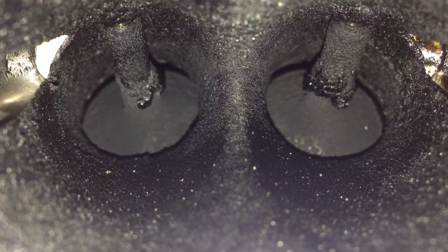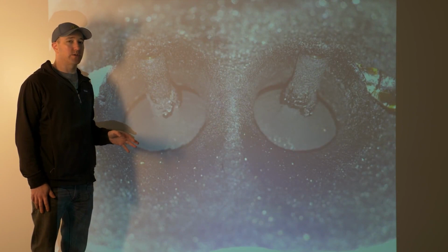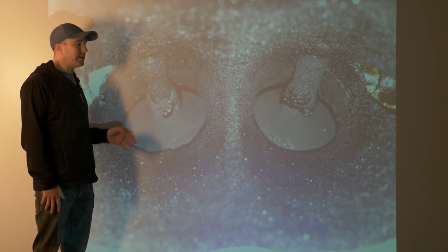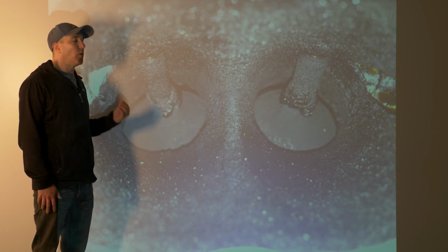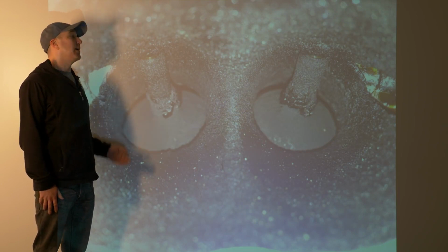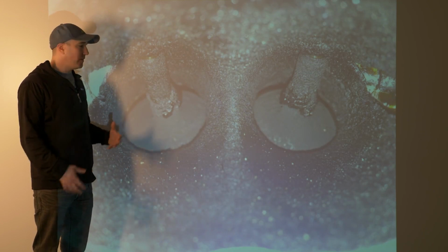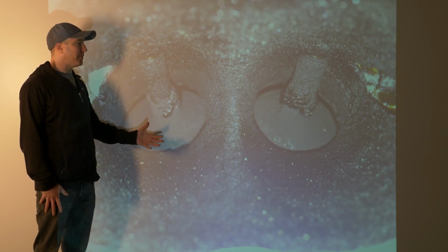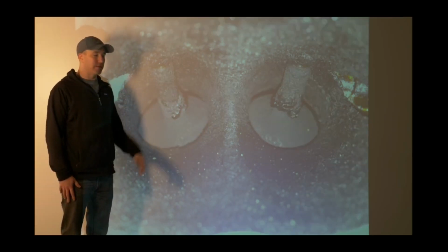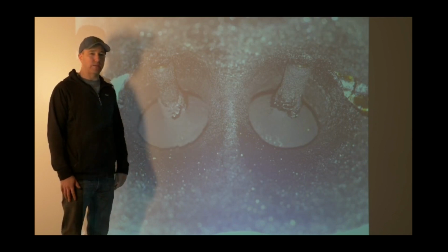The other thing that it can cause, and it's worse on turbocharged direct injected motors, depending on the manufacturer and the turbos they use, is that oil can leak past the turbo seals and then get in here as well. So it's like a triple threat. With no way to wash this off, this is the end game. This is what you're going to have to deal with as an owner of these cars over the long term.